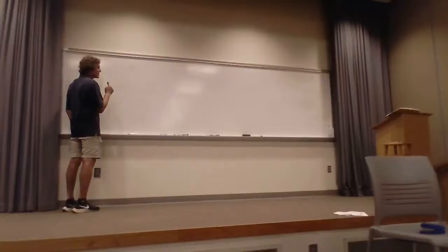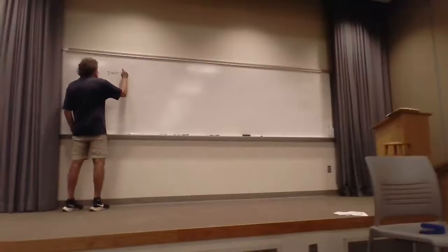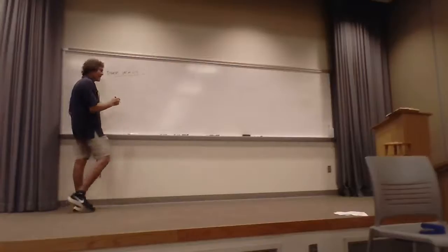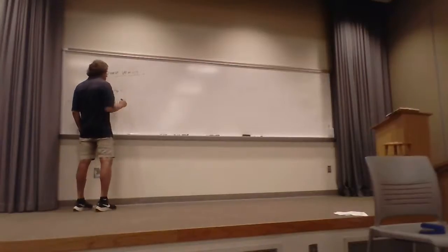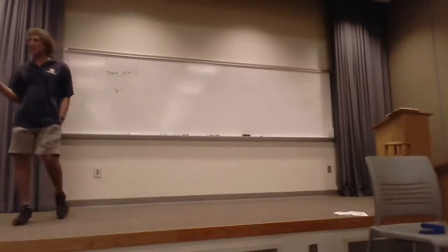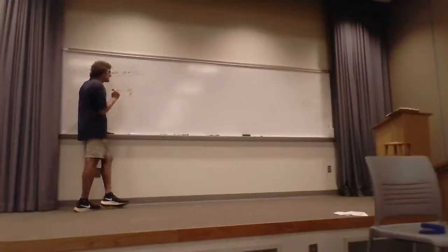Okay, back to this thing. So now we're going to talk about phase velocity. Without boring you, do you remember how we got phase velocity in general for waves? Well, we knew the argument of the cosine, omega t minus beta z, was the phase of the wave, right? And the phase had to be constant, so we backed out that the phase velocity, dz/dt, was equal to omega over beta. That was the most general form.